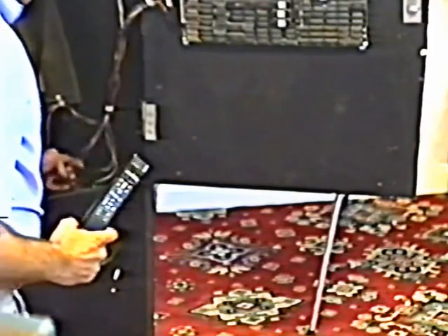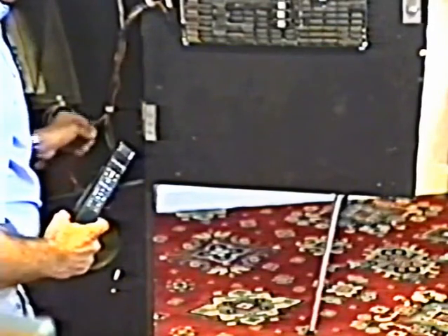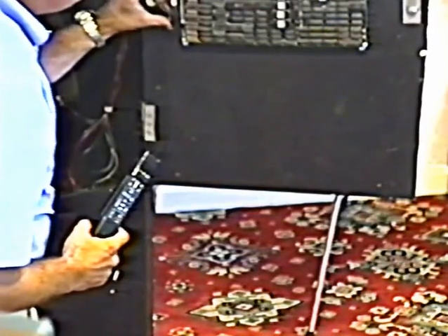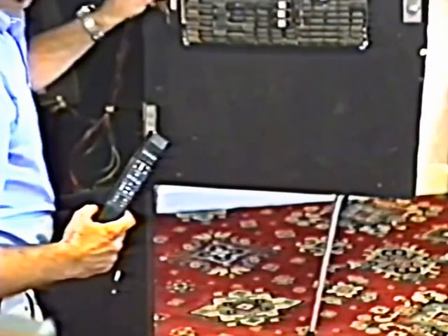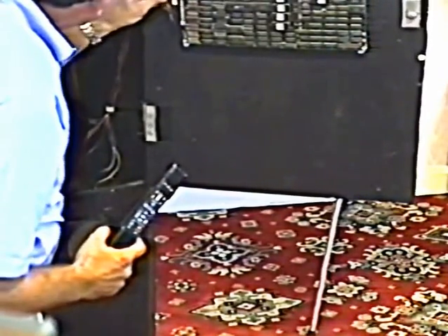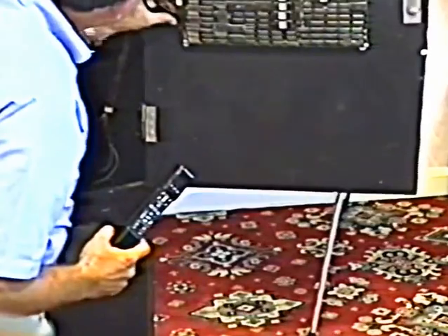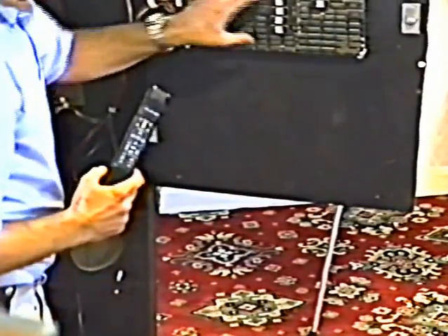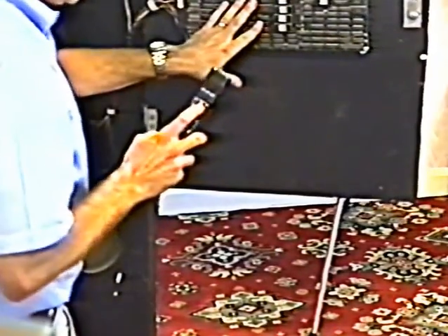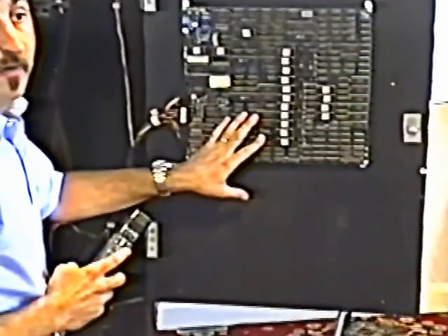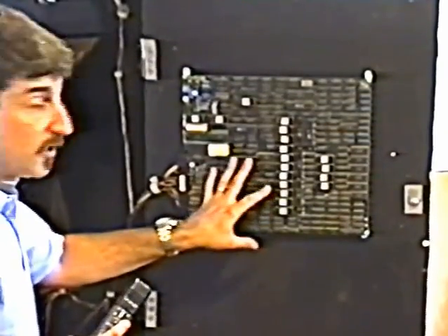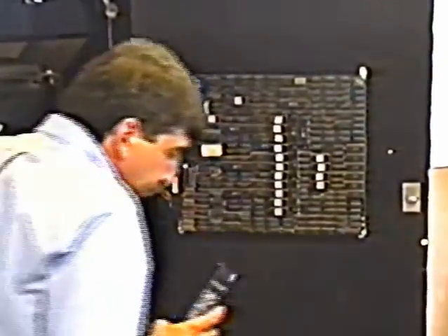So by the time the current gets out of this power supply, through these wires, through this connector, which is not even very tight actually, it's pretty darn loose in fact, through this connector and onto the logic board, it's real easy to lose a few tenths of a volt. So it's real important that we measure the voltage on the logic board.